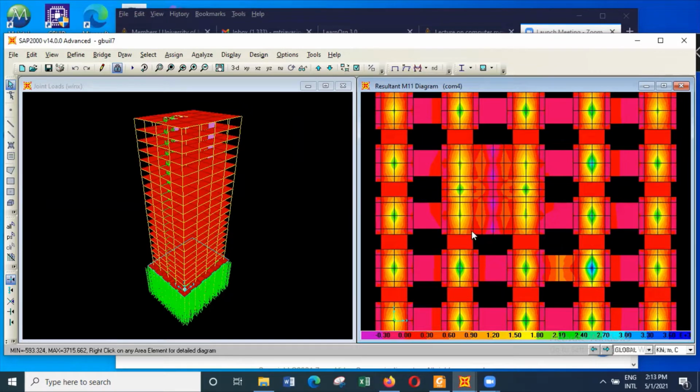And you can see the bending moments in these connecting shell elements are very small, and these connecting shell elements are used to represent the ground slab. So here also I should be filling and then applying the loads, but I didn't want to spend much time on those things. Those can be done by you. So basically you can represent the ground slab at this particular level, but these slabs would not be heavily loaded, they are very lightly loaded.